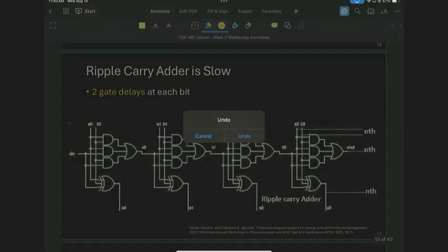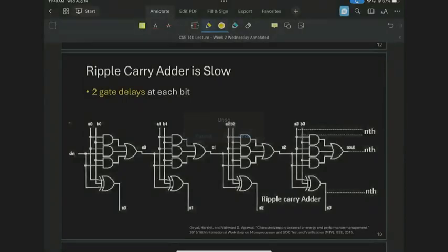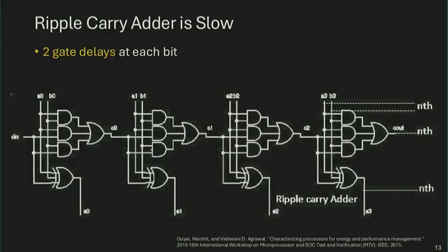And this is a full gate level implementation. This is a full implementation of a 4-bit adder. We have an XOR as the sum logic, and a 2-level sum of products as my carry logic, and they form a chain. And this circuit is kind of slow, because whenever you send in inputs, your inputs need to go through the longest path to complete the operation.